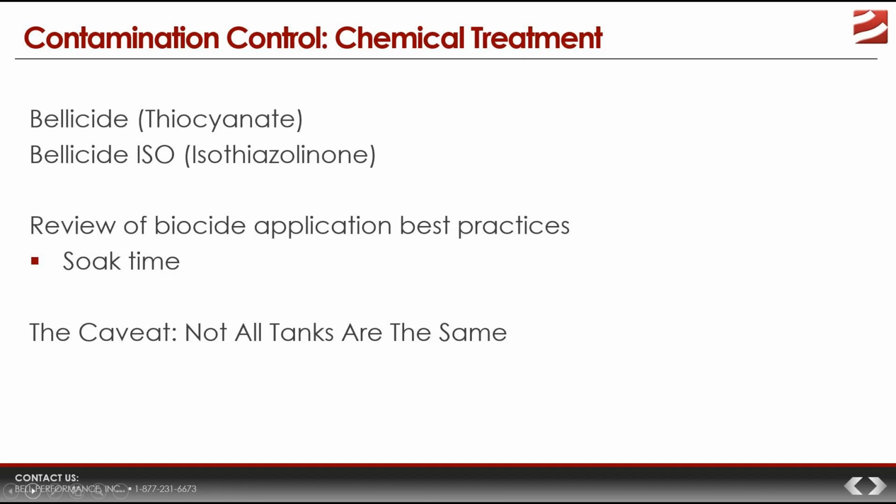And of course, if you have a really, really heavily infected system, then you would plan to see plugged filters until the killed biofilm has been flushed out from the system. Alternatively, if a fuel polisher is using this, then they would apply the biocide, they'd give it the soak time, and then they would filter everything, and that would take care of that problem.